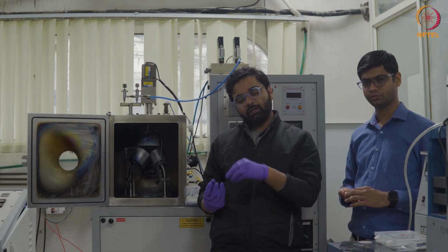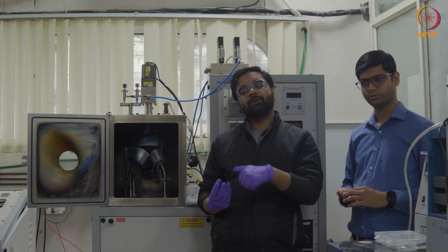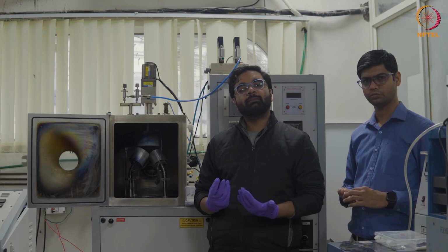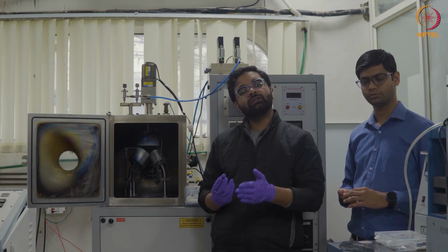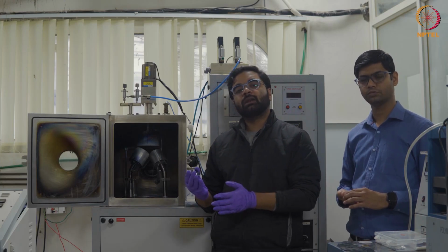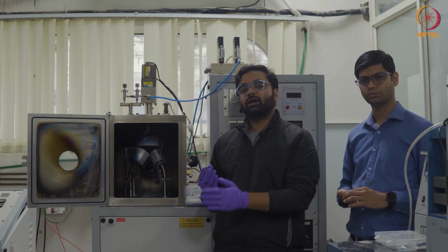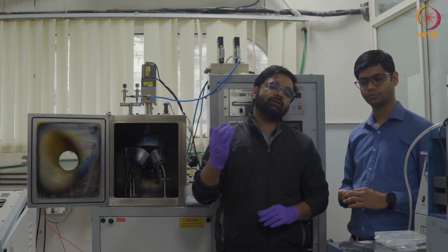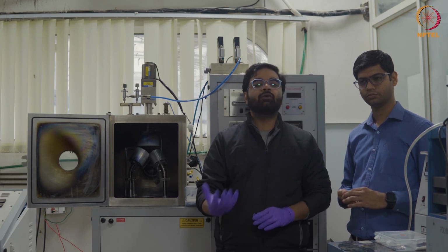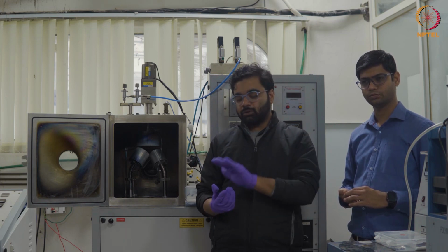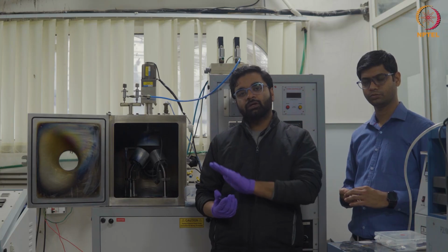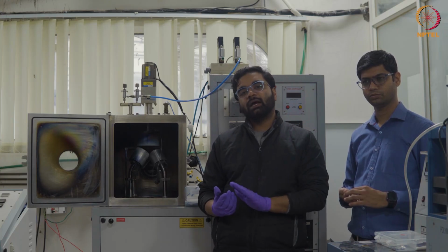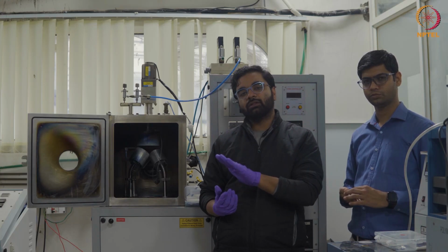So we do a spin coating, which of course is again optimized. We normally do it in the range of 5000 RPM to 8000 RPM for 100 seconds. The 100 seconds comprises an acceleration time of 10 seconds, a deceleration time of 10 seconds, and a holding time of 80 seconds. The material is then spin coated and present on the surface.